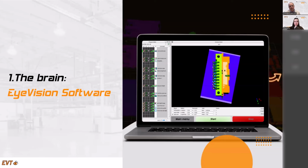You can also use USB. It has some limitations. One has to think about it. If the machine vision system is very close to the application, USB 3 is also very good. If you have multiple cameras, maybe you have to think about whether the system supports so many ports for the USB cameras.